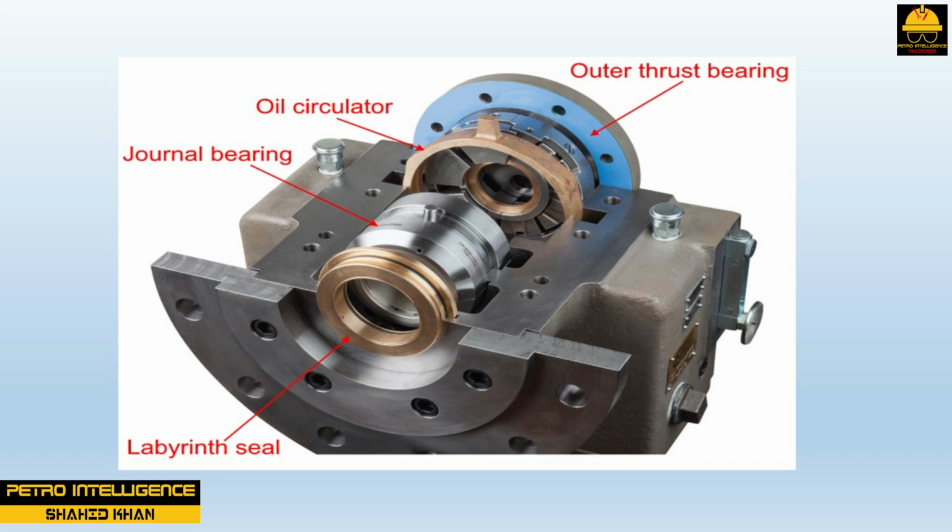During operation, the thrust bearing draws oil up under the rounded edges of the pivot shoes. As hydraulic pressure builds, the shoes tip slightly, allowing more oil to be drawn under the collar. At normal speed, the shoes have a slight tilt, which is sufficient to accommodate an oil wedge. This oil wedge separates the shoes from the collar.